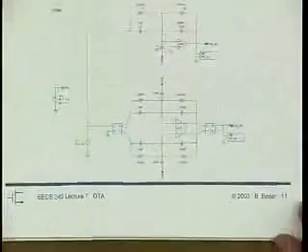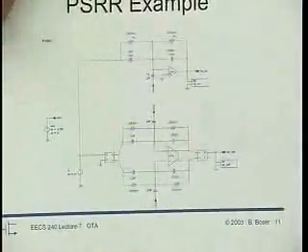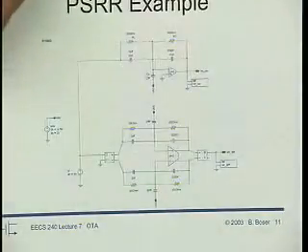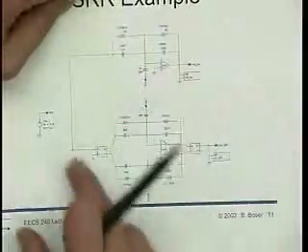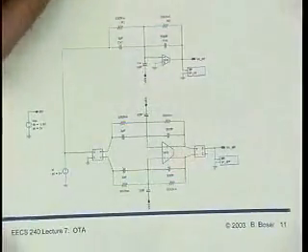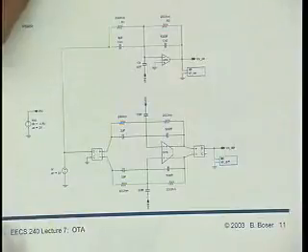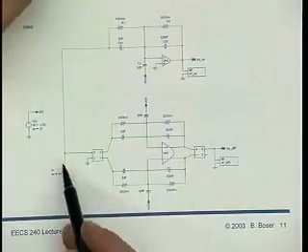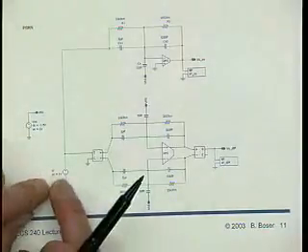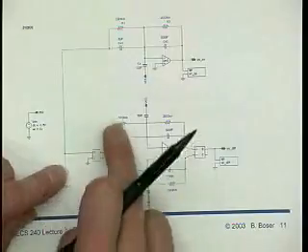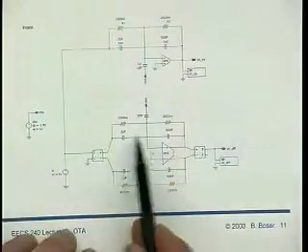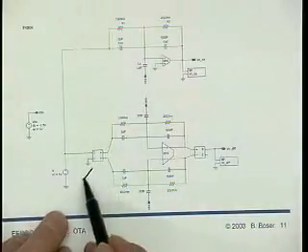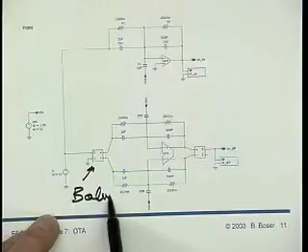I made an example here, a little bit trivial, just to make that point again. So first of all, in this example here, I have a single-ended amplifier, and then I also have a differential amplifier. So now my input signal is a differential signal, and because the input of the amplifier is, of course, two individual VI plus and VI minus inputs, I use a balun to do the translation.